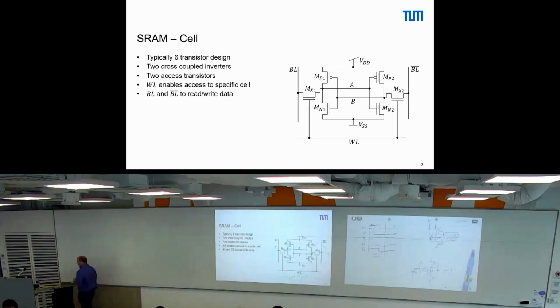Now, to ensure that that does not happen, you have at bitline inverse, I just draw it like this, a connection to some sense amplifier. The purpose of a sense amplifier is that a small delta V is translated into a large delta V dash, which is actually then 0, 1 or 1, 0.